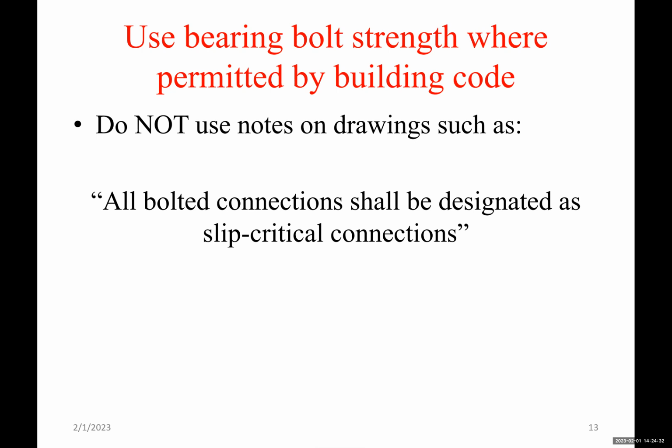So use slip critical connections where it is required. I mean, there are cases where you need to use slip critical. Other than that, use bearing type connections because they are also cheaper than slip critical connections.